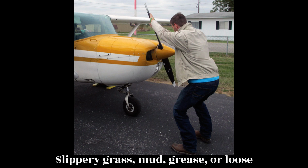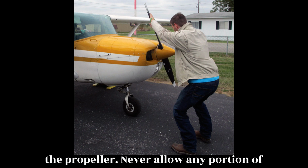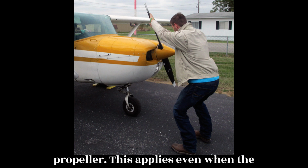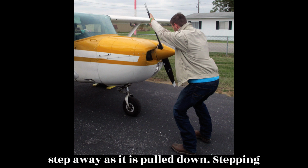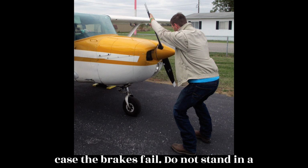Slippery grass, mud, grease, or loose gravel can lead to a fall into or under the propeller. Never allow any portion of your body to get in the way of the propeller. This applies even when the engine is not being cranked. Stand close enough to the propeller to be able to step away as it is pulled down. Stepping away after cranking is a safeguard in case the brakes fail.